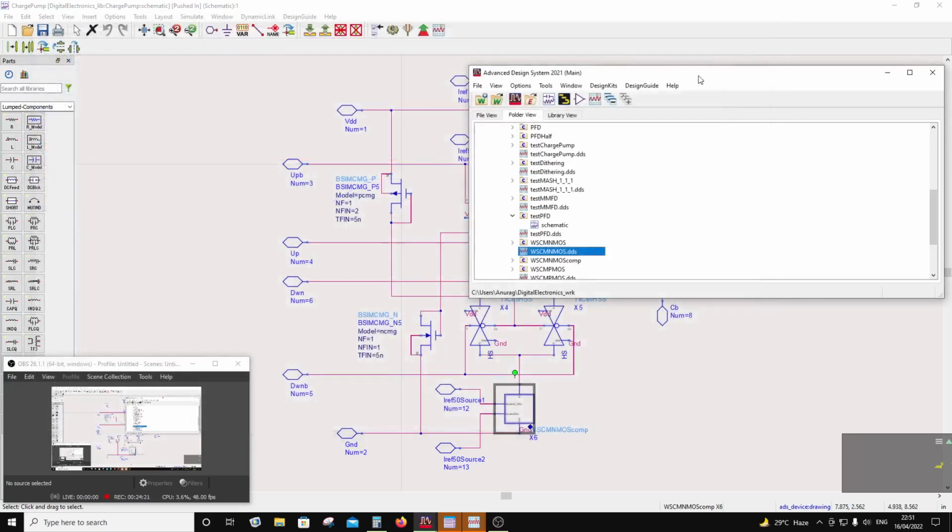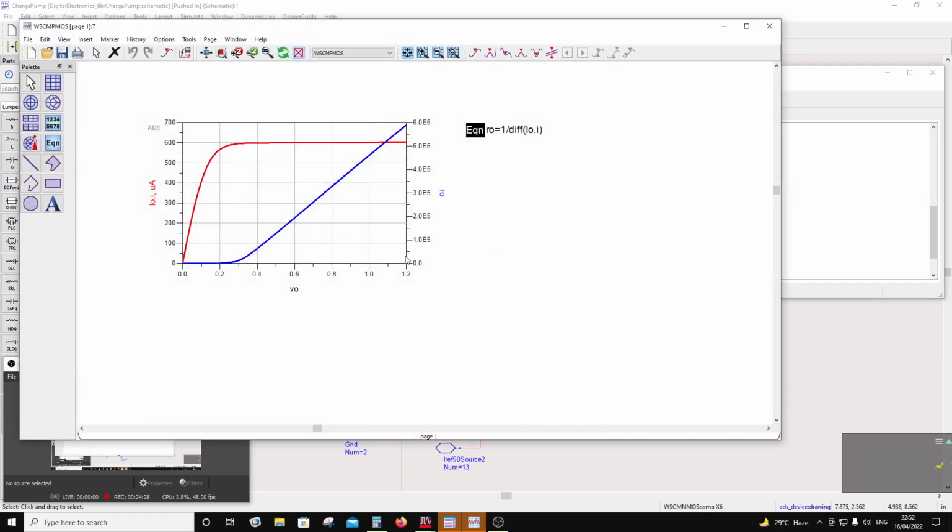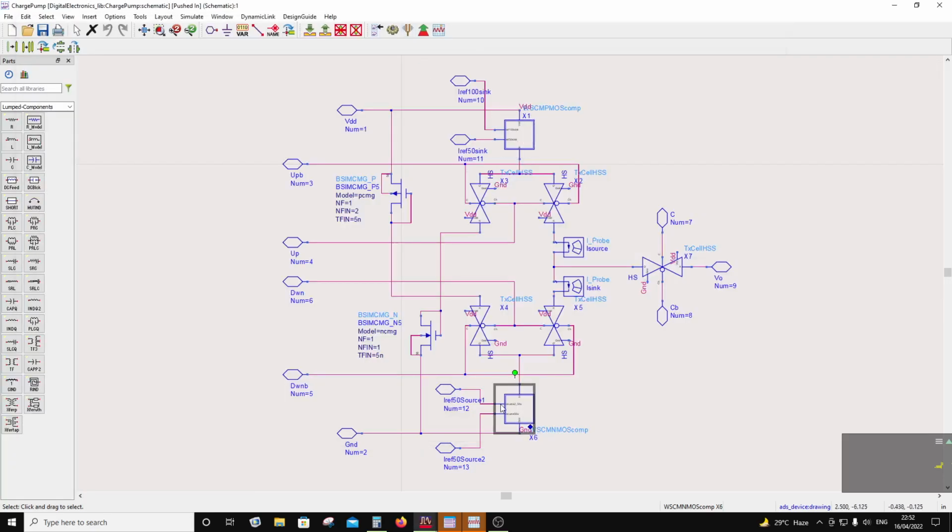So that's the NMOS. And if I go to PMOS and look at the PMOS, again, it's operating from 1.2 volts, so I'm losing 0.2 volts, after which there is a high impedance, right? So it's of the order of again 100 kilohertz to 600 kilohertz. So you have to be in the high impedance region. So I'm covering the entire range of the VCO by providing proper high impedance current sources and sinks, right? So this is how the charge pump is designed.